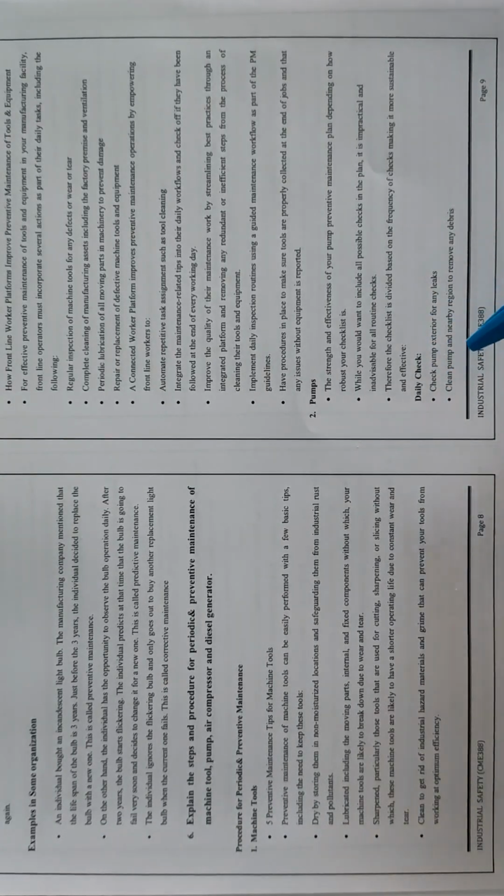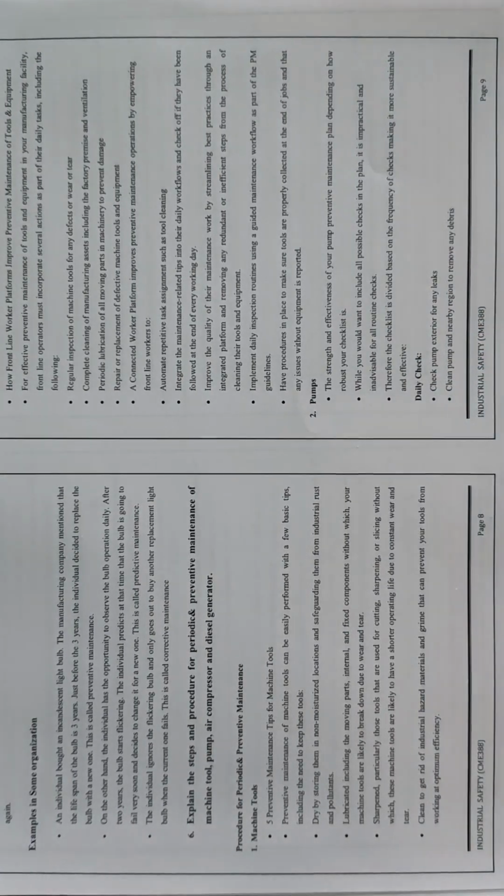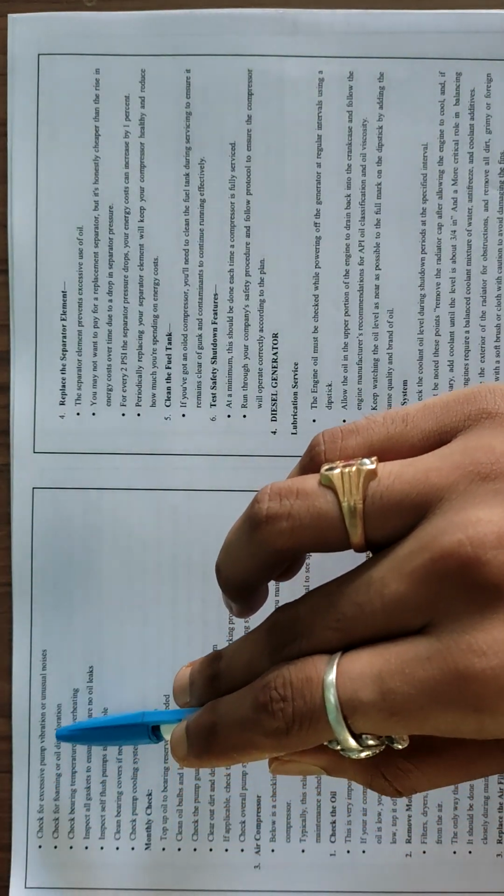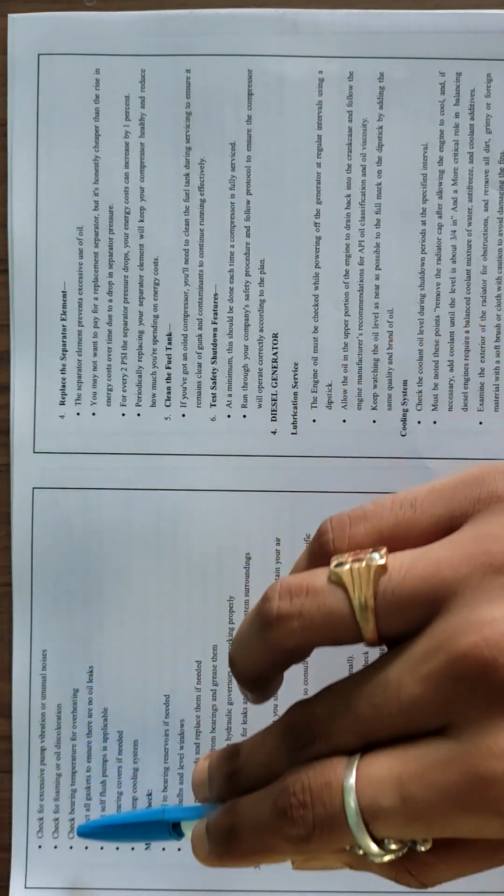Daily checks: check pump exterior for any leaks, clean pump and nearby region to remove any debris. Check for excessive pump vibration or unusual noises.